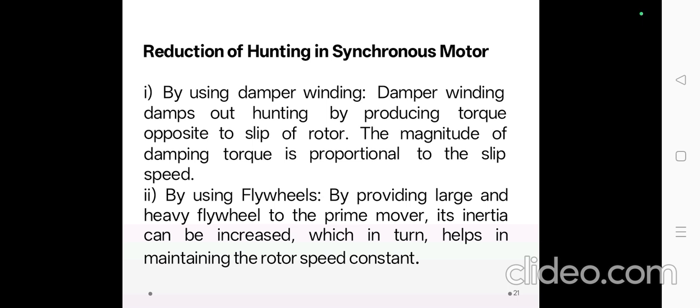This increases the cost. The large current means more copper losses and poor efficiency. Large current causes large voltage drop in transmission lines, alternators and other equipment. They result in poor regulation. To compensate such drops, extra equipment is necessary, which further increases the cost.